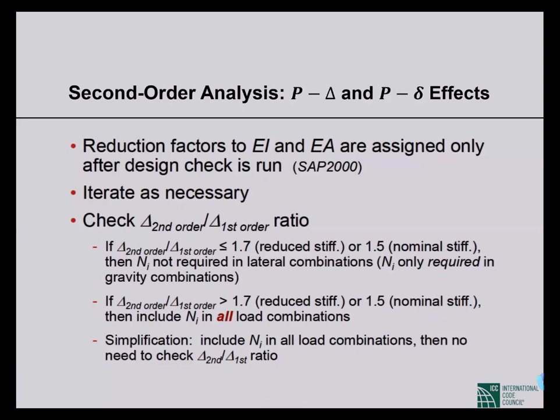And when we run again for different load combinations, remember we run for load combinations, not only for dead load or only for lateral load. So for different load combinations, that may change your design. When it changes your design, you have to iterate this process again, because every time there may be a change in this sway ratio, second order sway by first order sway ratio.